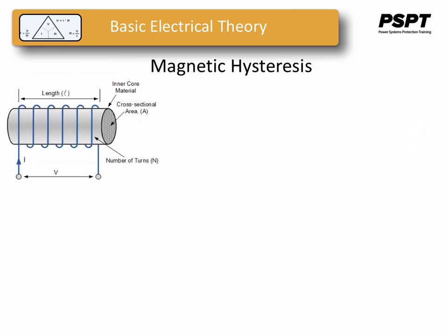Another quirk to confound our analysis of magnetic flux versus force is the phenomenon of magnetic hysteresis. Hysteresis means a lag between the input and the output in a system upon change of direction. In a magnetic system, hysteresis is seen in a ferromagnetic material that tends to stay magnetized after the applied field force, which is the current, has been removed from the circuit.